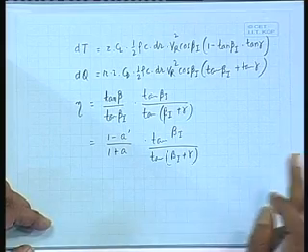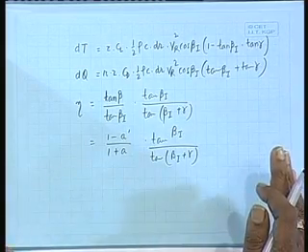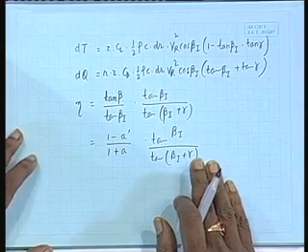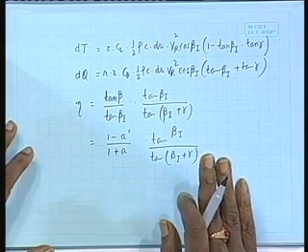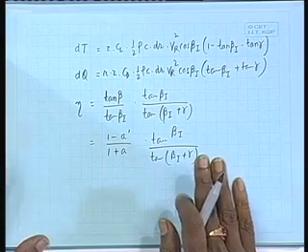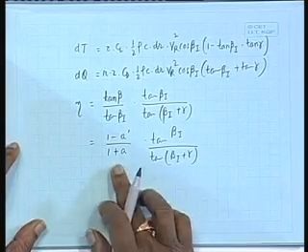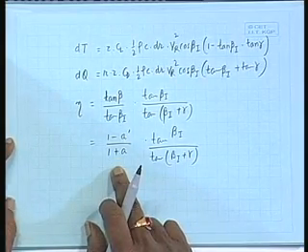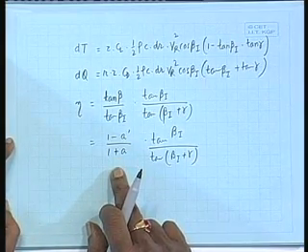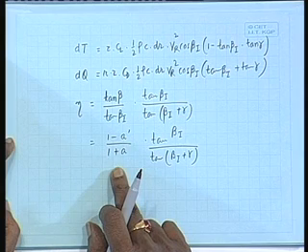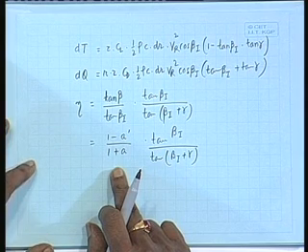Just see, previously we said that the efficiency would be 1. Now you put the same condition, that is, there is no drag, that is gamma is 0. If you put that, then you get efficiency same as what we had found in the impulse theory, momentum theory with rotation.